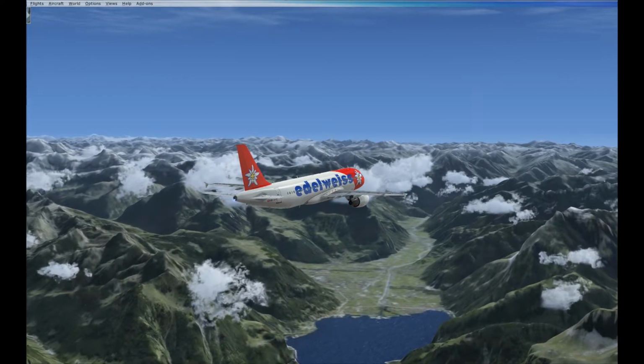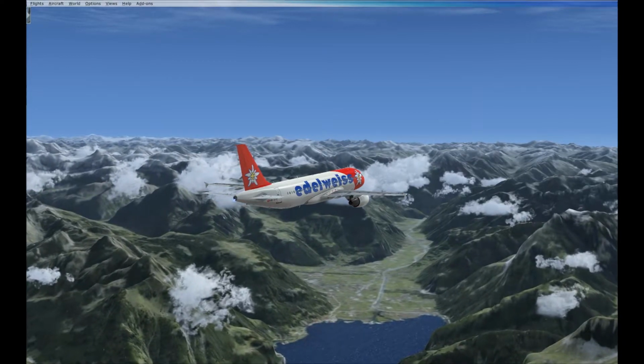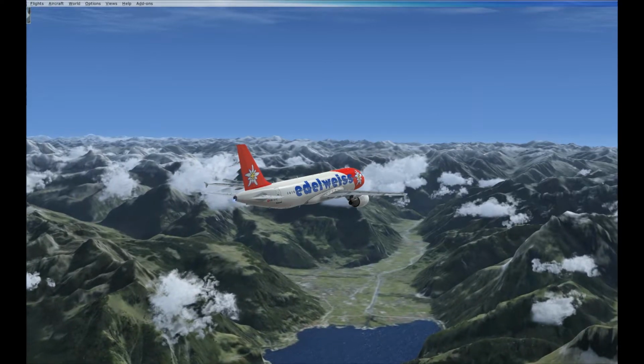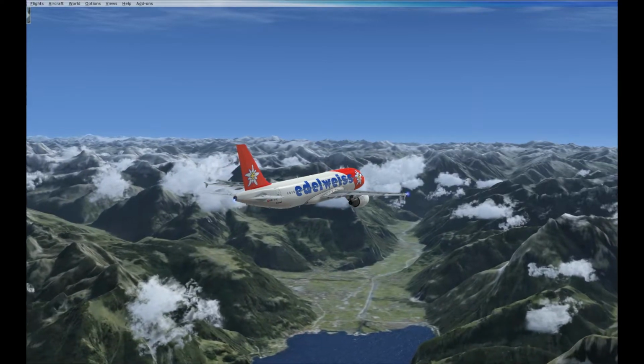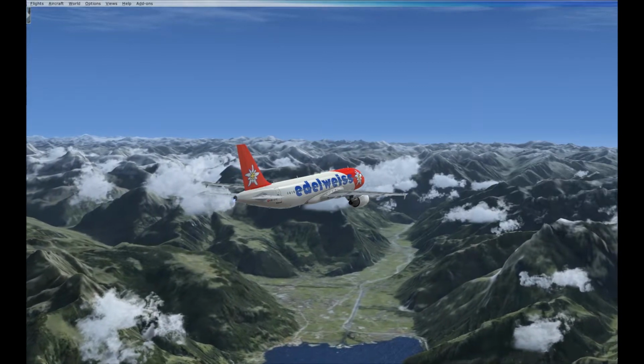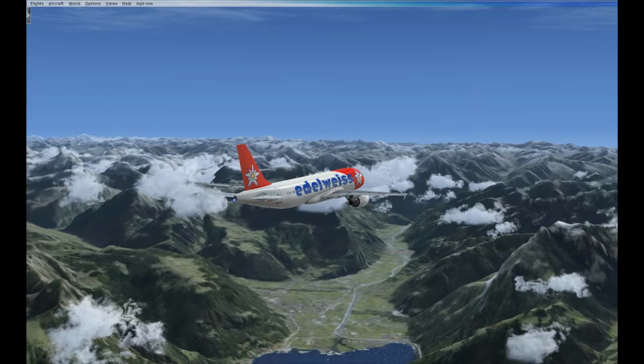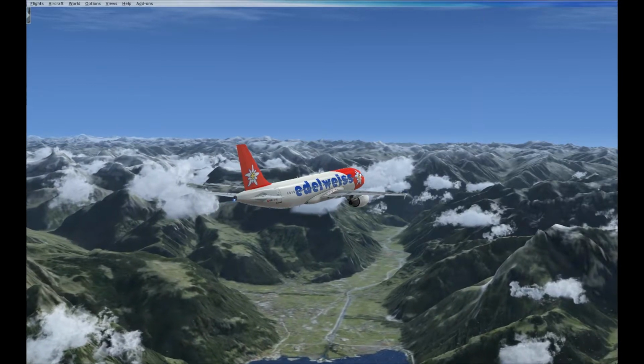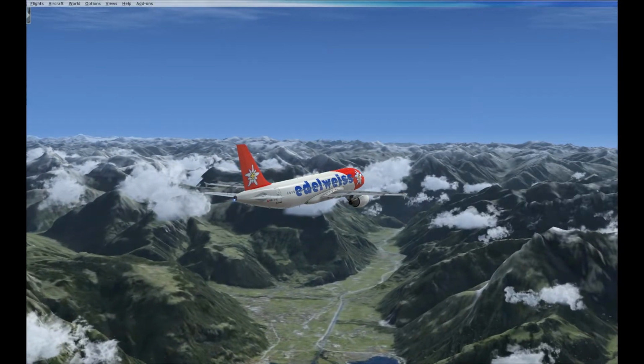It requires a relatively low landing speed. We are going to have to extend flaps and landing gear to produce drag on the aircraft, and we need to make a fairly steep final approach, around an angle of about 6 degrees compared to the standard one of 3 degrees.